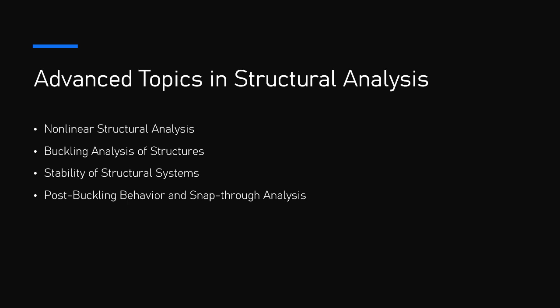10.4. Practical considerations in design. 1. Structural safety. Understanding and accounting for post-buckling and snap-through behavior is crucial in preventing unexpected collapse or failure. Design codes for structural systems must consider these nonlinear behaviors, especially for slender elements or flexible structures. 2. Redundancy in design. Providing redundancy in structural systems, e.g., multiple load paths, can help mitigate the risks associated with snap-through and post-buckling behavior.